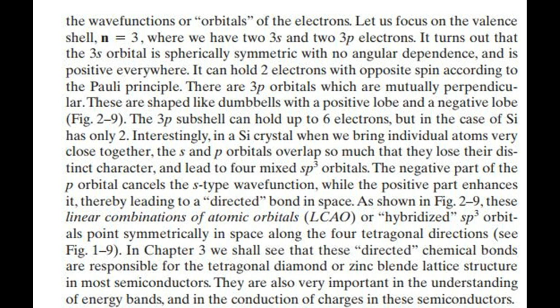Interestingly, in a Si crystal when we bring individual atoms very close together, the s and p orbitals overlap so much that they lose their distinct character, and lead to 4 mixed sp3 orbitals. The negative part of the p orbital cancels the s-type wave function, while the positive part enhances it, thereby leading to a directed bond in space. As shown in Fig 2.9, these linear combinations of atomic orbitals, LCAO, or hybridized sp3 orbitals point symmetrically in space along the 4 tetrahedral directions, see Fig 1.9.